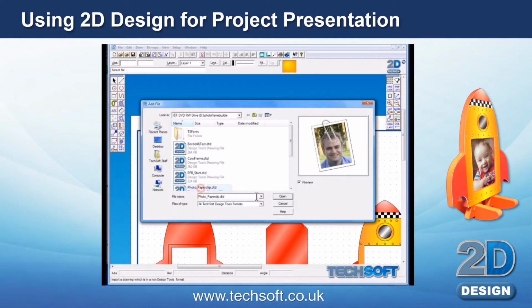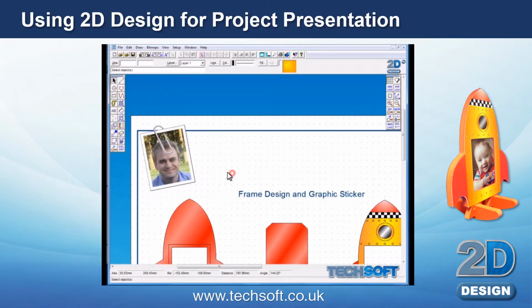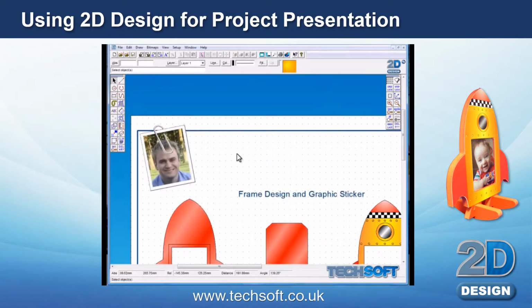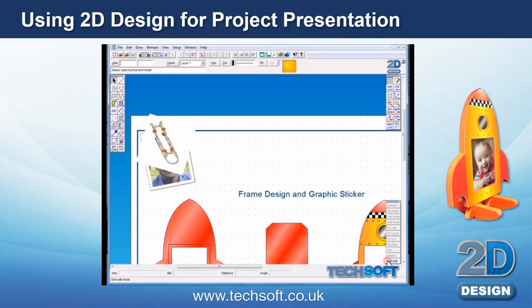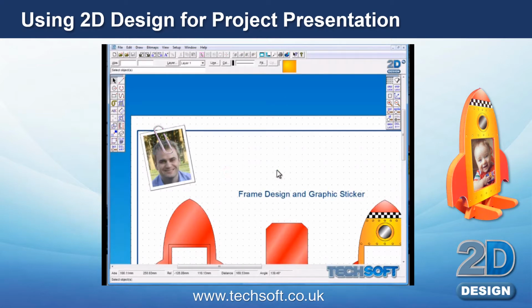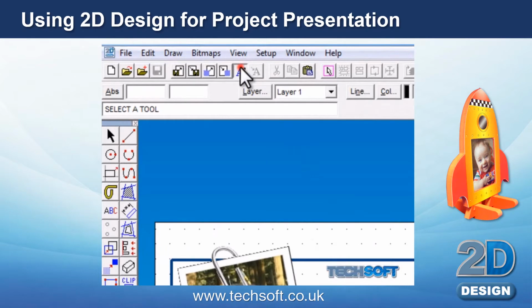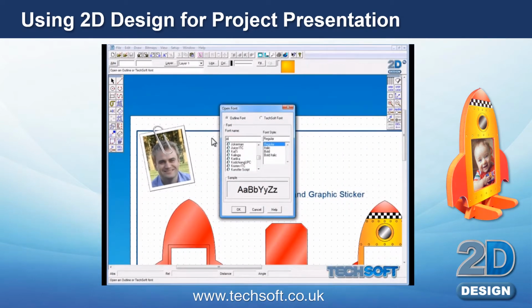Add the file Photo Paperclip. Select the photo and choose Bitmaps, View, Change Color Properties. The bitmap's colour properties can be changed if required. Select the paperclip and choose Start Edit. As you can see, the paperclip has already been clipped and part of the bitmap masked. Now we're going to open a font. Any font can be opened and then edited in 2D Design version 2. We'll choose the font Jokerman. This font has started to be edited and just needs one more letter to be changed.